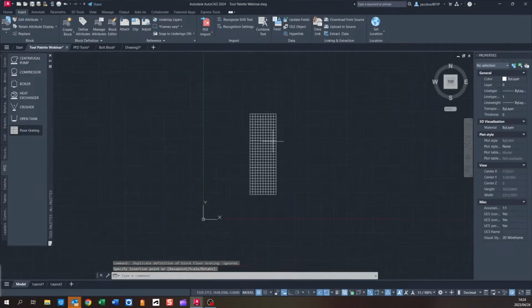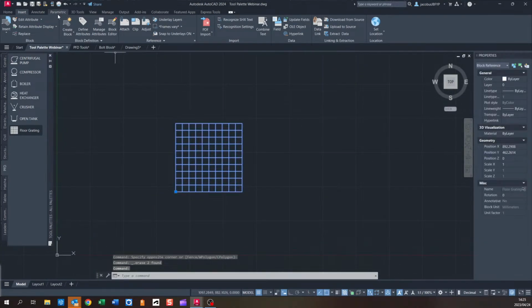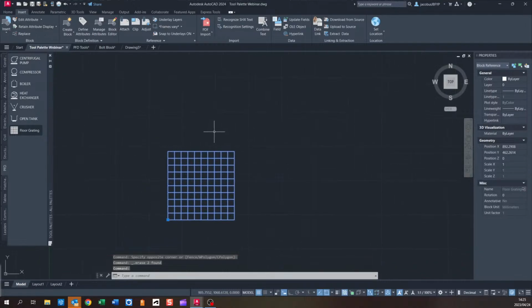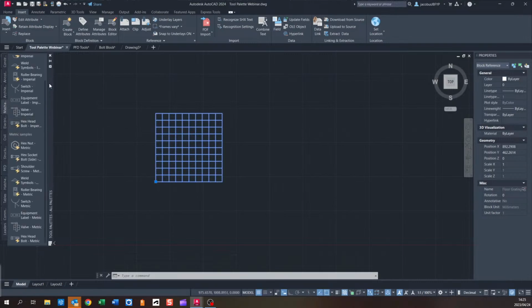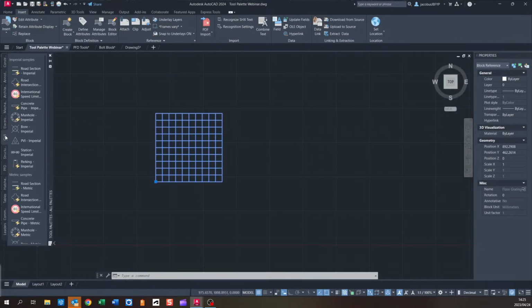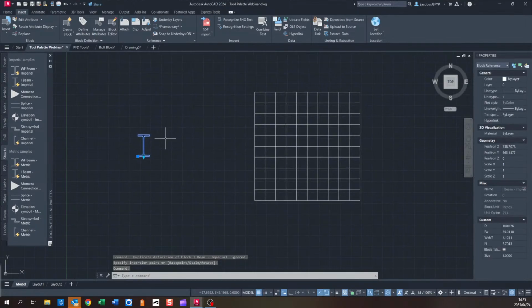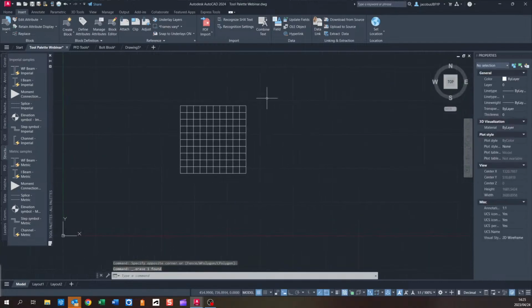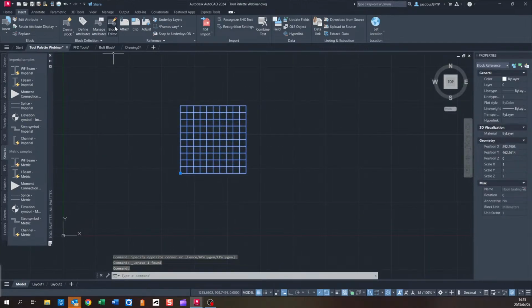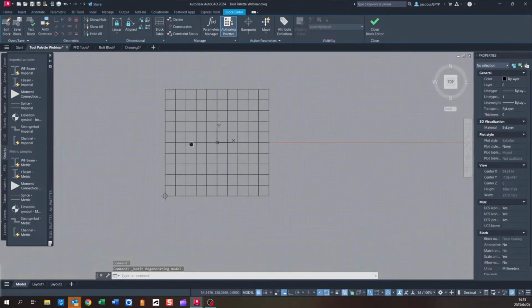Okay, all right. So now, lastly, I'm going to take you through a short process of making this a dynamic block. Think back to items such as the hex nut, or let's take the I-beam, where clicking on it gives you that drop down, or other commands where you're able to stretch it and so forth. All of that happens within the block editor. So I'm going to click on this, click on block editor. That's the one I want, and I'm going to open this up.